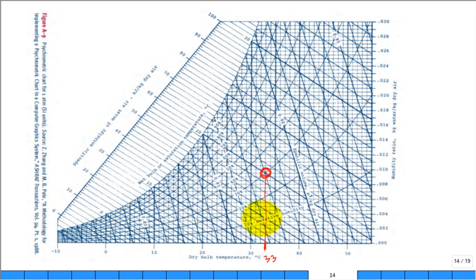And you're going to put it to a cooling coil. As you put it to a cooling coil, it will not condense immediately, it'll stay at the same humidity ratio, but it'll just drop the dry bulb as it goes across that cooling coil. And where did it say it stopped cooling at? At what temperature? 15? Is this 15C right there? And so if you just stay horizontal and you come across to 15, you stop at 90% relative humidity.